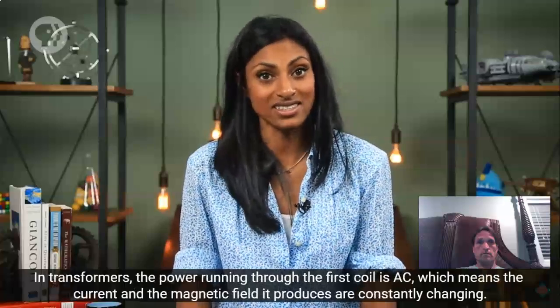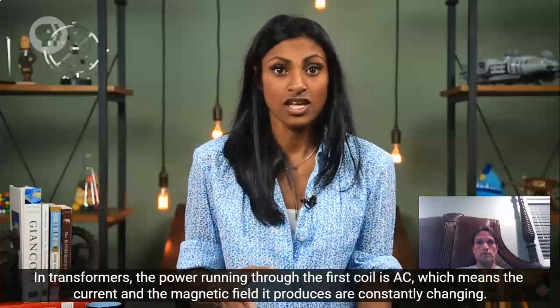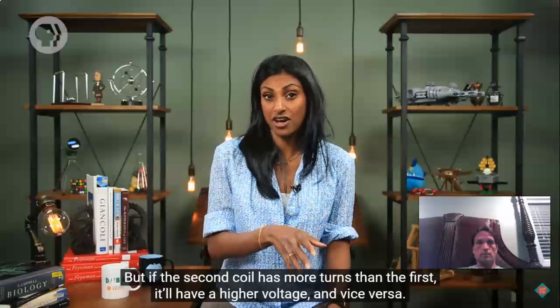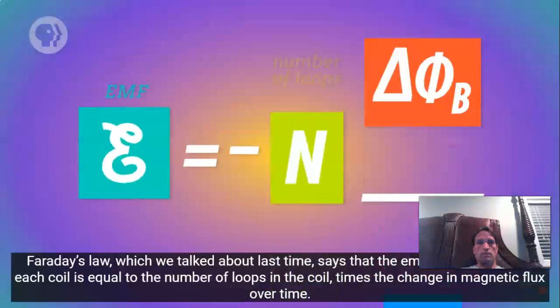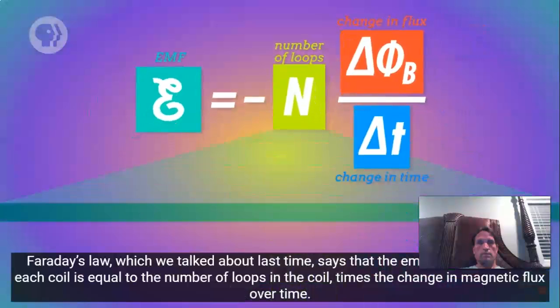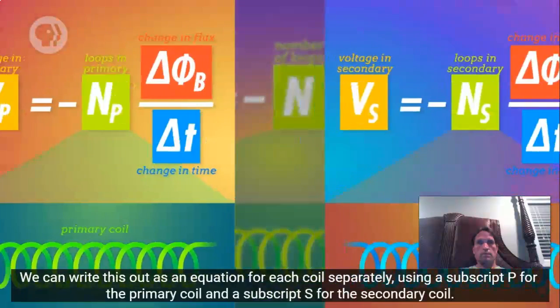In transformers, the power running through the first coil is AC, which means the current and the magnetic field it produces are constantly changing. So an EMF is induced in the second coil. But if the second coil has more turns than the first, it will have a higher voltage and vice versa. Here's why. Faraday's law, which we talked about last time, says that the EMF or voltage in each coil is equal to the number of loops in the coil times the change in magnetic flux over time.